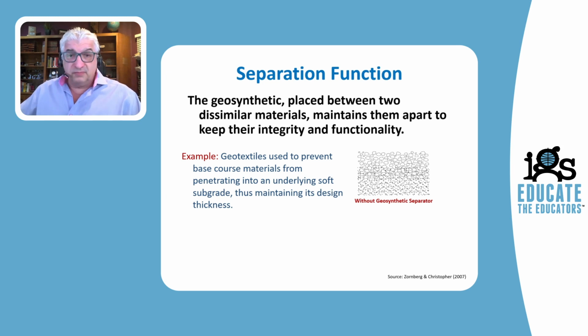For all practical purposes, a mixture of gravel and clay will behave much more like a clay than the gravel. And the gravel is the component of a roadway that provides the stiffness that we need because we are designing a roadway to minimize deformations.